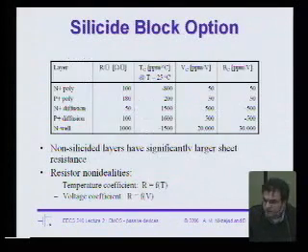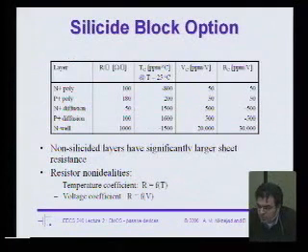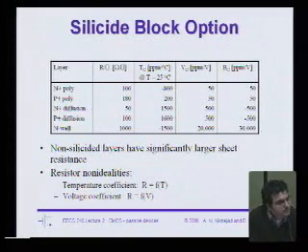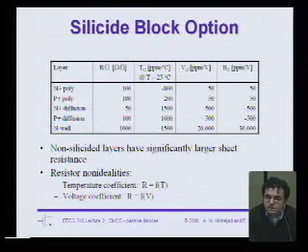You'll notice here that the temperature coefficients for these polys actually have different signs. And what are we going to do about that? Is that a problem? Yes. Can you use them to cancel each other out? Yeah, that's right. That's actually a nice feature. In fact, whoever designed this process probably did this on purpose.